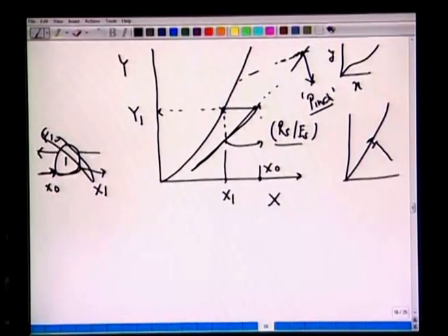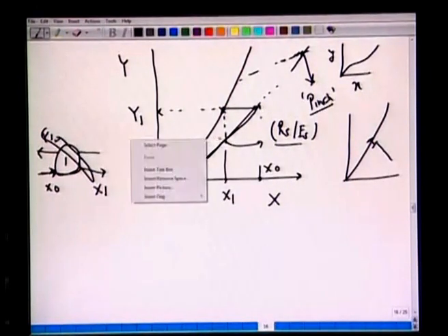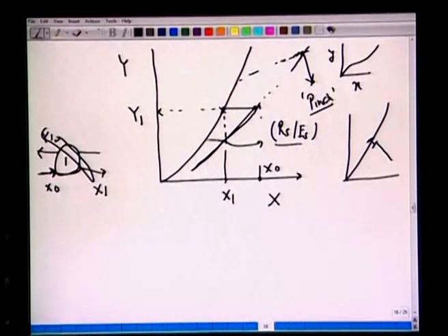We can take this x1, get back to the operating curve, which will give us x2 or y2. Again y2 will be in equilibrium with x2 here. We can mark the x2, get back to the equilibrium curve to mark this point y3, and we have this x3 here.